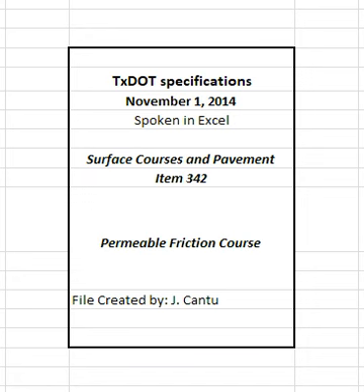Perform any necessary tests to ensure contractor or department-owned RAP is appropriate for use. The department will not perform any tests or assume any liability for the quality of the department-owned RAP unless otherwise shown on the plans. The contractor will retain ownership of RAP generated on the project when shown on the plans. The coarse RAP stockpile will contain only material retained by processing over a 3/8 inch or 1/2 inch screen unless otherwise approved. Fine RAP is not allowed in PFC mixtures.